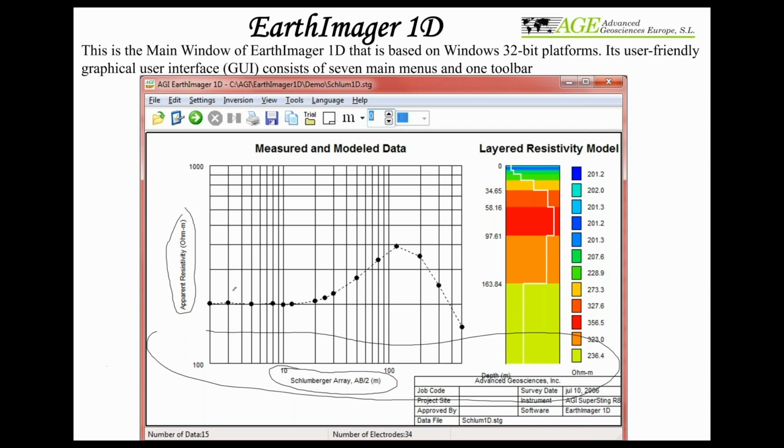If you see anything like this, doing the measurement like this point, for example, or this point, that means these are noisy data. There can be many different reasons. Maybe it's a long geometry, or you really have noise at that point. So you can just go and repeat until you get a very nice point. That's what's important in the field. Just go with a transparent log-log paper. Draw all your measurements on this paper during your measurement. Make sure that all your data is of good quality. I mean, they get a good smoothing.